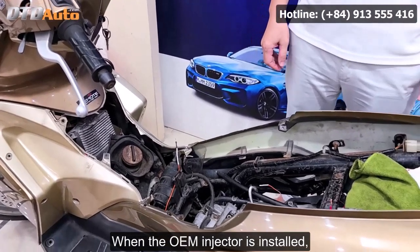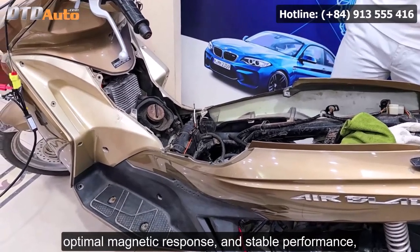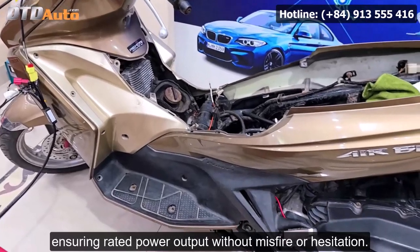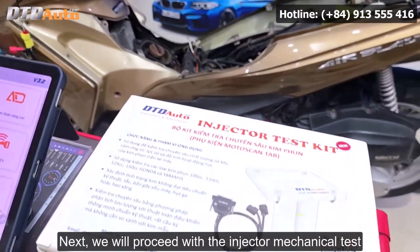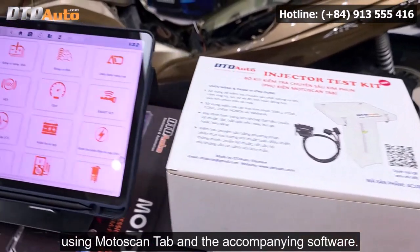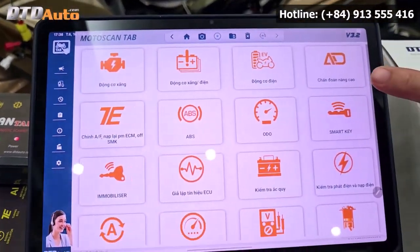When the OEM injector is installed, the engine maintains consistent fuel flow, optimal magnetic response, and stable performance, ensuring rated power output without misfire or hesitation. Next, we will proceed with the injector mechanical test using MOTOSCAN tab and the accompanying software. Please follow the on-screen instructions in the MOTOSCAN tab software.